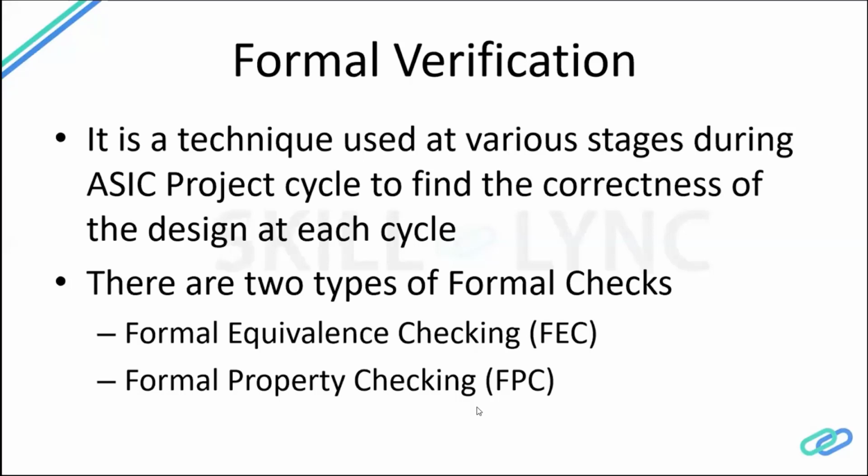While doing the synthesis, we use something called constraints. In the constraints, we define the input delay and output delay based on the RTL. We also insert DFT checks. When we add all those constraints and run the synthesis tool, the tool might decide that whatever logic we have written is redundant logic. So the tool might optimize it or completely remove it. That is where we do a formal equivalence check. What it does is compare each point, that is the output point, called out points.